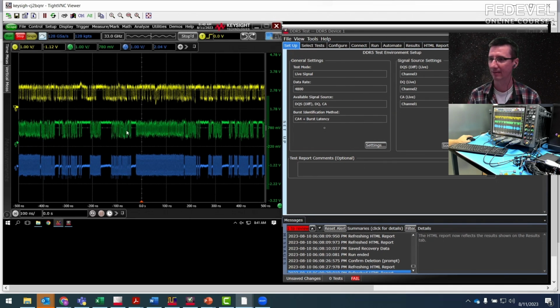The way that I'm probing is closer to the DRAM because I have that interposer, that special fixture. Therefore, I would say the larger amplitude part of the signal is the read cycle. And then the smaller signal that went all through the PCB, through the via transitions and connector, has some signal degradation.